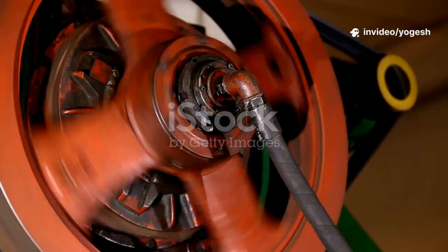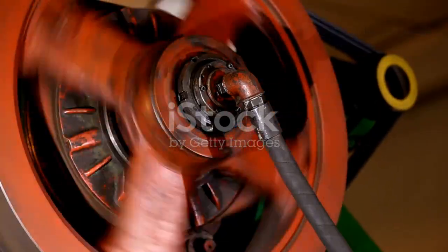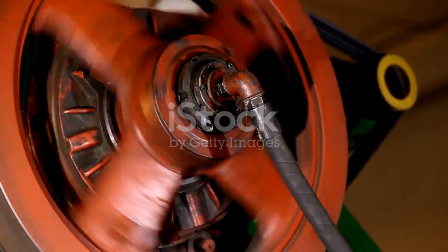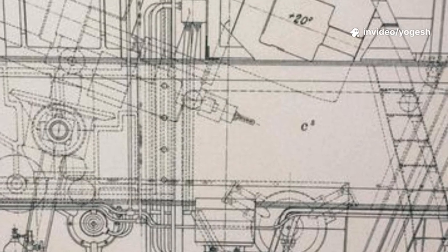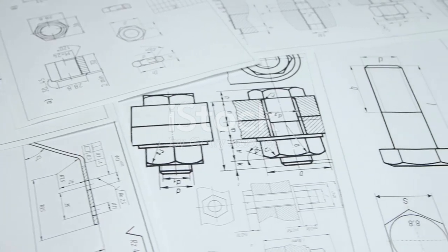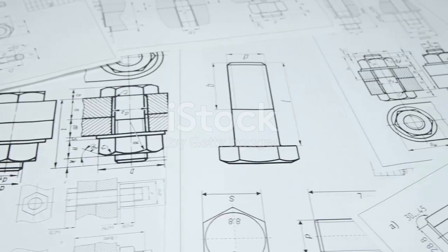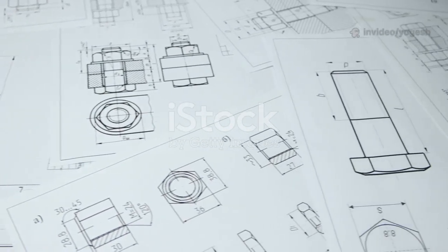Make a note of the spring's function in maintaining proper belt tension. The spring ensures the belt stays tight, compensating for any stretching over time and keeping the system running efficiently. For any custom mechanical parts, create separate detailed drawings. These detailed views provide exact specifications for manufacturing or 3D printing, reducing the risk of errors.